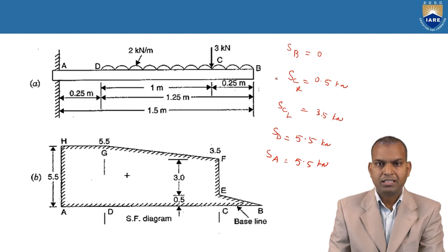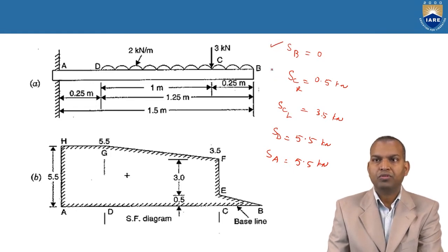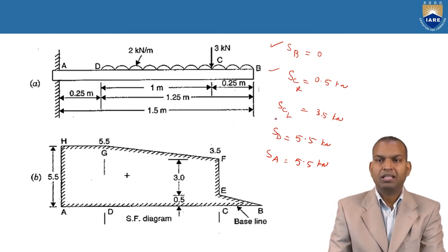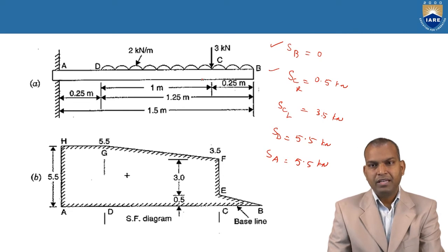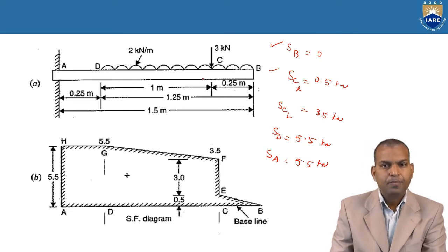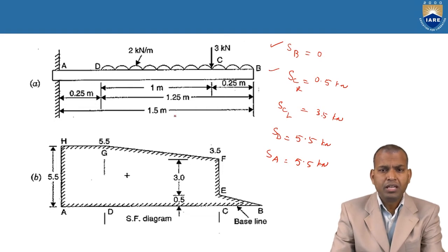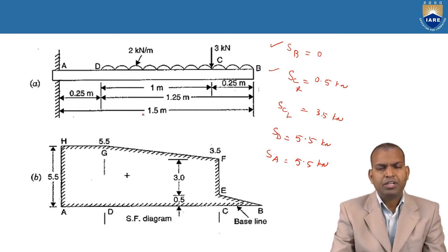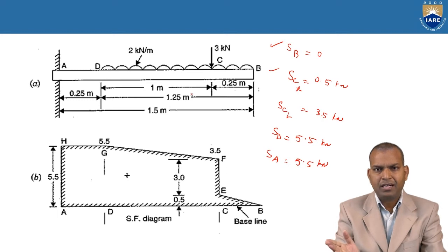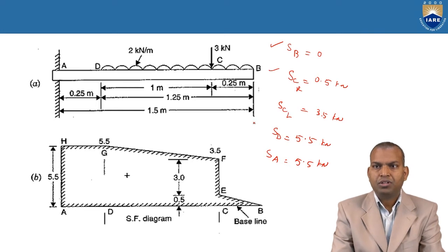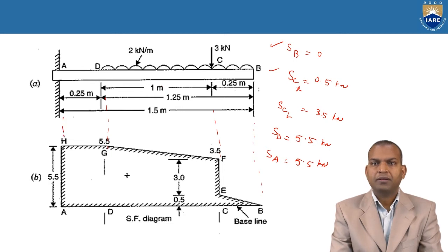Shear force sign convention. We observed those values at point B, point C right, and point C left. Why have I marked point C right and point C left? Because you can then understand how the shear force varies on the right side and the left side of point C. Now if you draw the projection lines, this is the loading diagram, this is the load diagram, and this is the shear diagram. Now these are the points. If you mark them on this, what will happen?